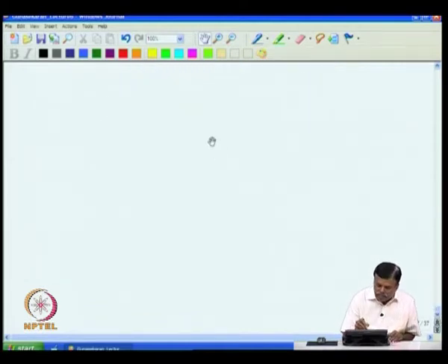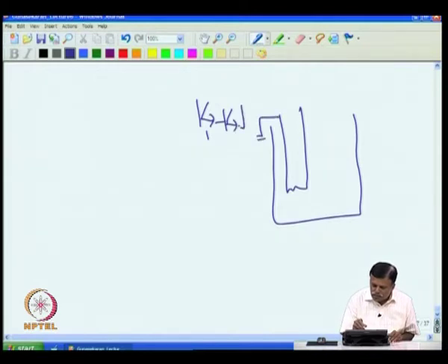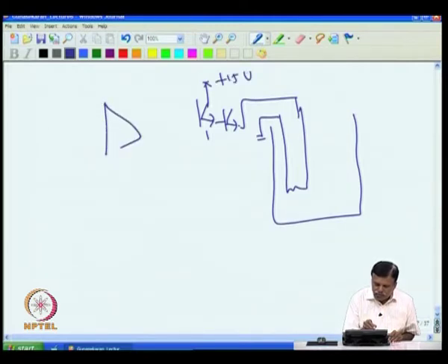See, I draw only the heater part and the last part. So you have the heater voltage here, and the heater is driven through a Darlington pair, and the heater voltage is given to this, and you have here plus 15 volt, and then this is the final op-amp output that is given to this, and this is the gain stage.